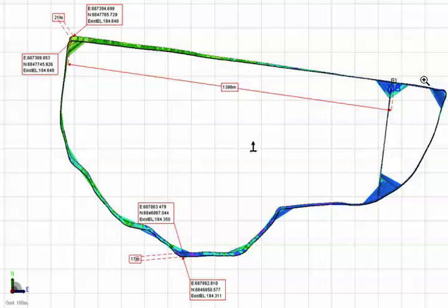Okay, so we've just done a survey with two different GPS brand RTK systems. One was a Trimble field level system using the survey plugin, and one was, I think, probably Integra Nordics or GPS Ag, the Australian name of the guidance system. So the black line is where the operator drove around the boundary with both systems following very closely so we could check the difference. And the master benchmark is here.